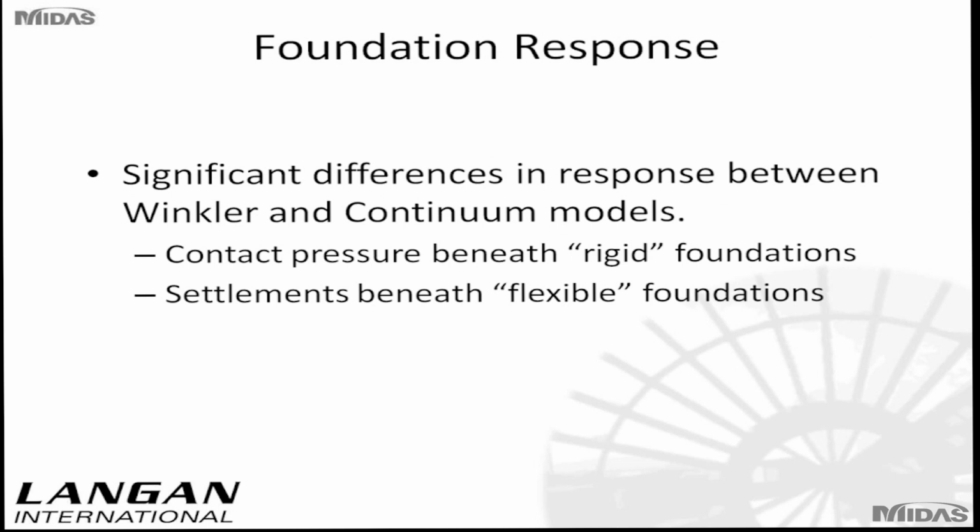Now, regarding the foundation response, there are significant differences between the Winkler and continuum models. And this can be demonstrated easily by examining two extreme situations, a rigid foundation and a flexible foundation. And we will see that the contact pressures and settlements between these extreme situations don't agree between the structural model and the geotechnical model. I'd like to note that even a 4-meter thick raft can be flexible depending on the loads from the superstructure and the dimensions of the raft.